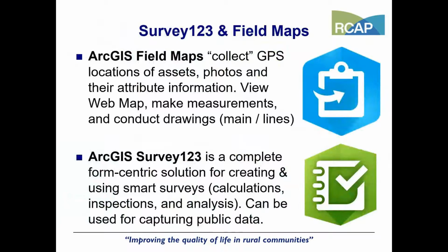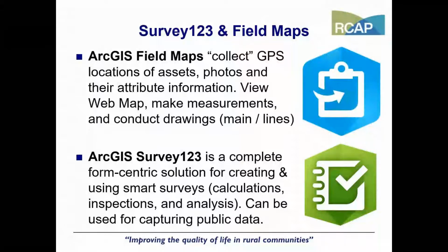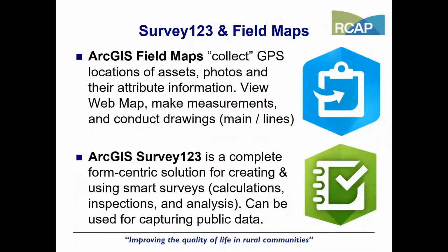So these are the two main Esri applications that we're going to get into today. Field Maps, that's what we use for the GPS data collection. So you can record the location of your assets, you can collect the who, what, where, why, when of them, you can take your photos, you can view those points, you can edit them, you can do measurements, which I find nice sometimes. Sometimes we know the distances between two manholes, so you can do measurements between two points. You can also draw on there any kind of water or wastewater lines. So that's, again, going to be used to manage your system, to collect those points, use it in the field to see where they're at, make some basic changes to them, take the photos.